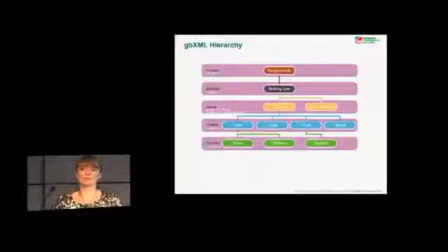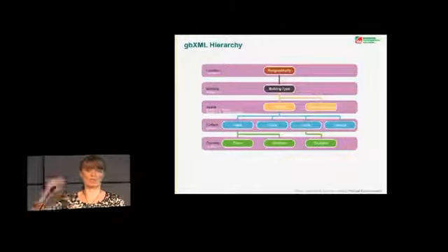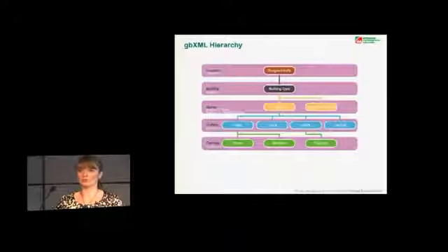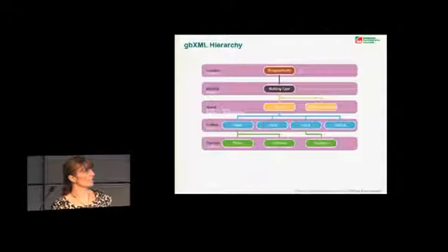We differentiate between rooms and shading surfaces because we want to be able to bring in elements. It could be louvers on the exterior of your building. It could even be an adjacent building to the one that you're doing your analysis on. We want those to come across. They will impact the building that we're looking at because they'll overshadow it and block solar gain, that sort of thing. But we don't want to include those in, for example, the carbon footprint calculation for the building that we're interested in. So we need to take account of them in such a way that the software knows they're there but doesn't include them in the carbon energy calculation.